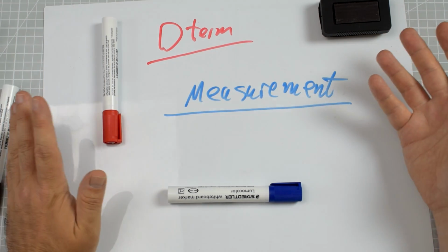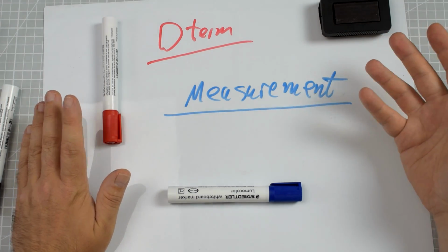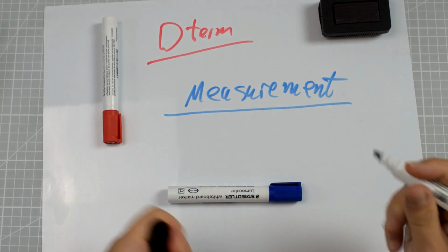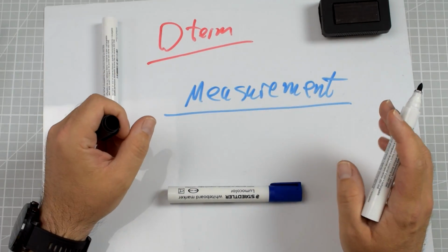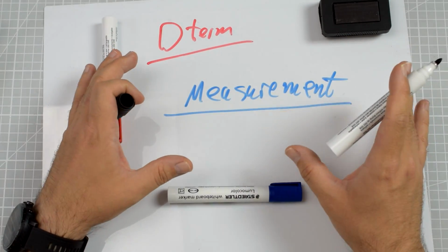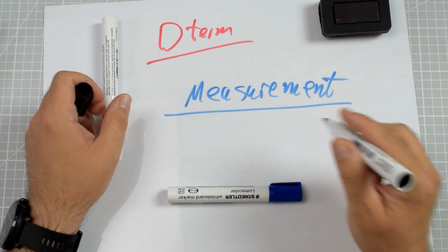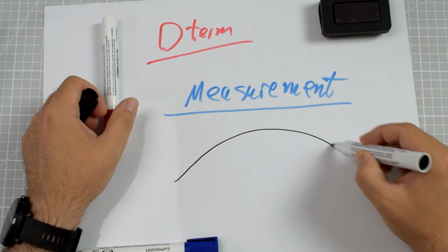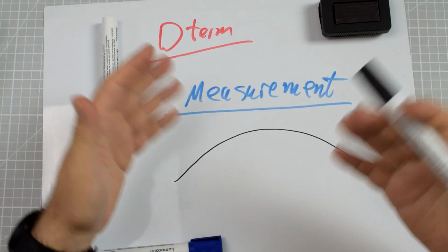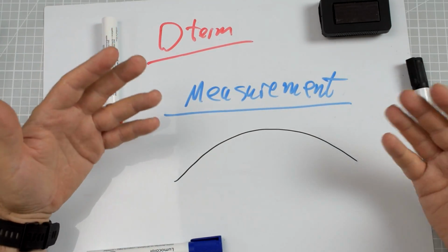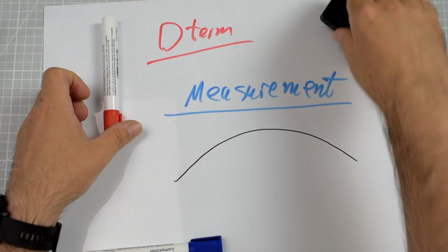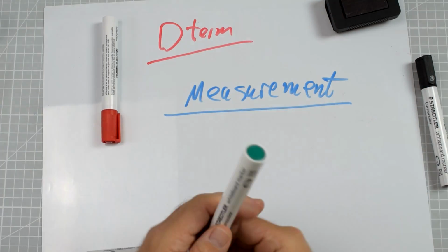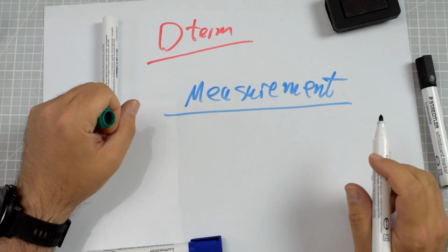There are applications, of course, when this is not a problem, but if, for example, we are into rapid drone flight with a lot of fast maneuvers, then computing the D term only from the measurement has the penalty that the input, even if you move your sticks very fast, will be mushy and slow, and it's definitely not what everybody expects.